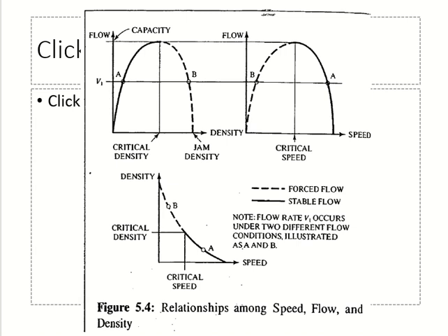So there is a point of density at which the vehicles are so many that they are affecting each other. They are not letting each other move. This is what you see in the busy parking areas. If I give you this much space, maybe you can park 3-4 vehicles here, but these 3-4 vehicles will not be able to move. What is my point? You can have an increase in density with a decrease in flow.